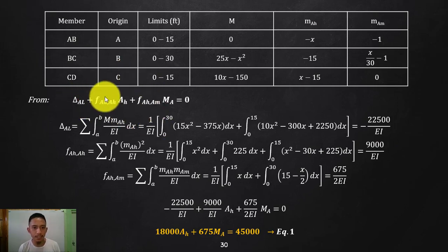Now, you need to find these small deflections. This one is due to the horizontal redundant, and this is due to the moment redundant at A. So we will not be using your big M in getting these values, since there is no effect of your actual loading. So what I will just be considering are your small moments.